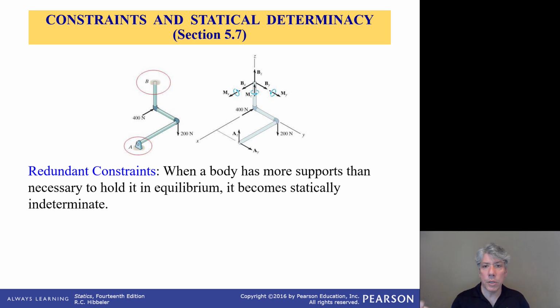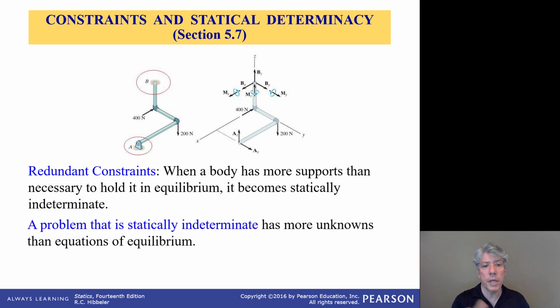Now, like I said, when we get to Strength of Materials, you'll learn about deflection, and you'll learn how we can include sort of a spring equation or a deflection equation, taking each of the members of the structure or the free body to act as if they were springs, which they do really. So watch out for redundant constraints and problems that are statically indeterminate. All that means is statics can't determine an answer for you for that particular problem.